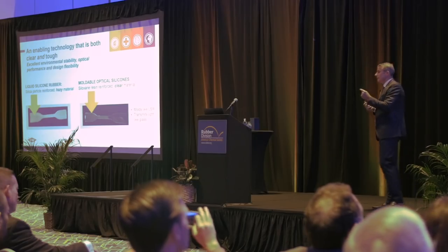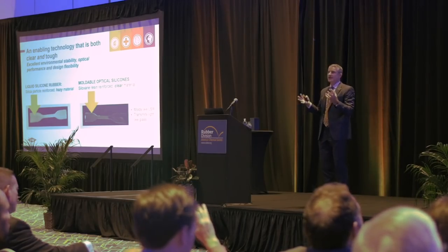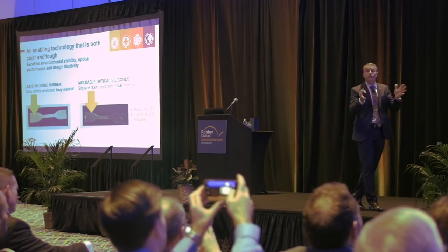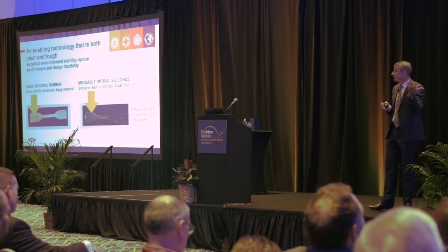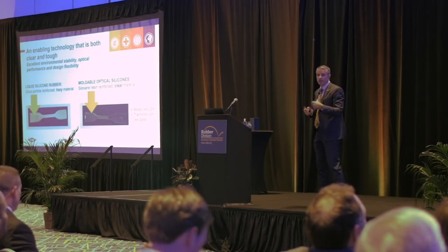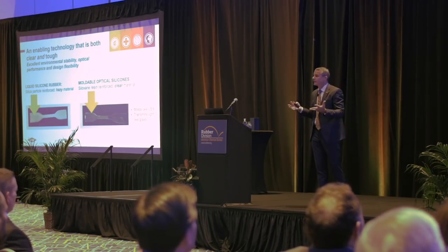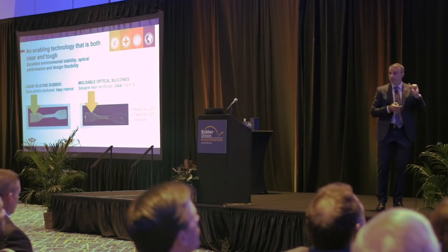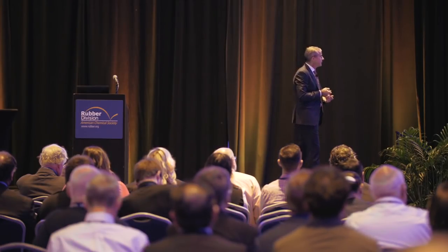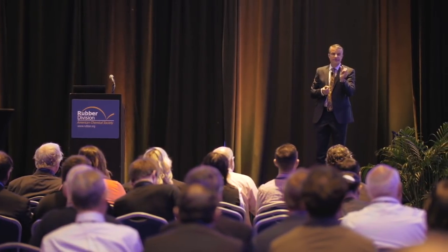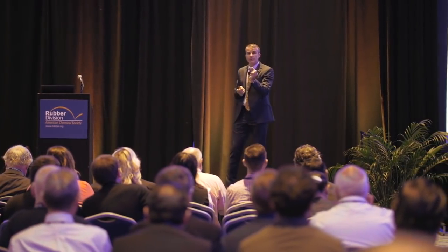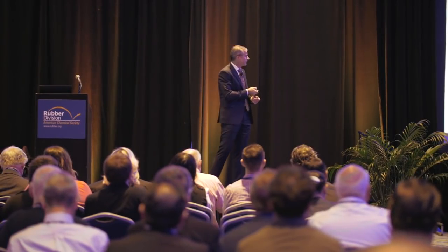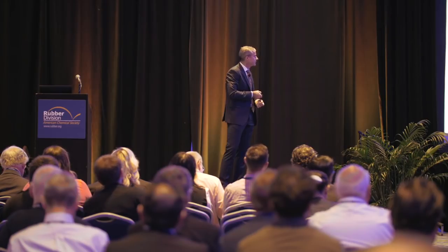Now, in order for silicones to be strong and tough enough, you have to fortify them. The way you do this is you typically put silica or fillers in there, most often some sort of silica, cubic silica, or what have you. The problem is those are micron-sized particles, and they lead to a non-clear system. So what we discovered is that if you take our internal resins that act kind of like nanofillers and put them in there, they give you structural reinforcement, but they do it below the wavelength of light, and now you get entirely, perfectly clear systems.